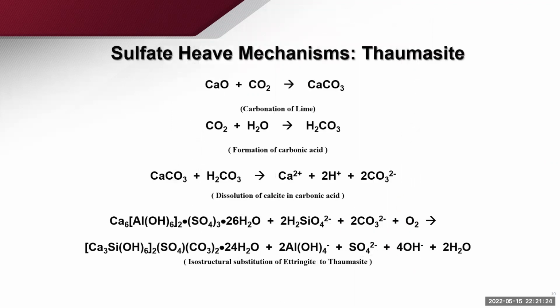With that, there's another mineral which one also has to check most of the time. It's called thaumasite. Thaumasite is worse than ettringite. As you can see at the bottom, this is the thaumasite formation reaction. But one good thing is this can only happen in very cold conditions. Unfortunately, that means in certain parts of North India you may have temperatures around 4 degrees centigrade, and this kind of reaction can happen. The ettringite converts into thaumasite. Thaumasite is known to be much more expansive than ettringite.